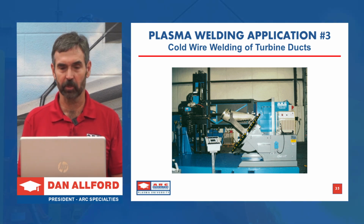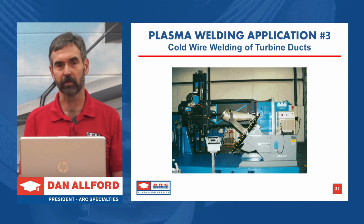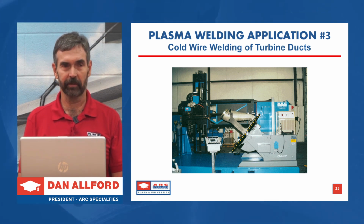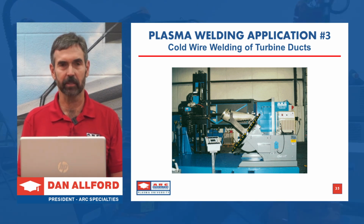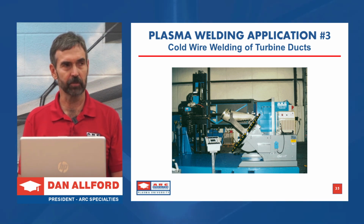So we're welding up turbine ducts for stationary turbines, and rather than keyhole them, we're melting through. So this is a little more like what you would do with a TIG, but again, there's an advantage with plasma. We're concentrating the energy and we're filling with wire. It's a great technique for welding up thin materials with 100% fusion on both sides.